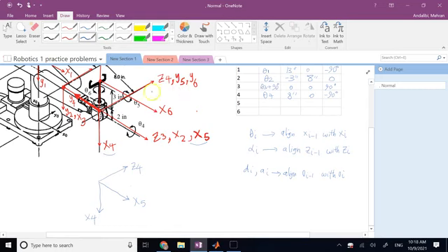And clearly, before even rotation theta 5 is happening, you need a 90-degree rotation, and that is opposite of the rotation positive for z4. So you need a negative 90 degrees before theta 5 can happen. So it is going to be what? Theta 5, and then minus 90 degrees. Good?